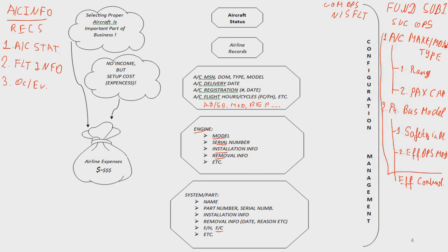And what we are doing, I call it configuration control. That's how we are controlling our configuration. What does it mean? For example, we're buying an aircraft and we want to fly ETOPS. One of the questions for ETOPS is the fuel crossfeed valve. The question is how many crossfeed valves we have, one or two? We have to know about this. That's configuration control, configuration management.